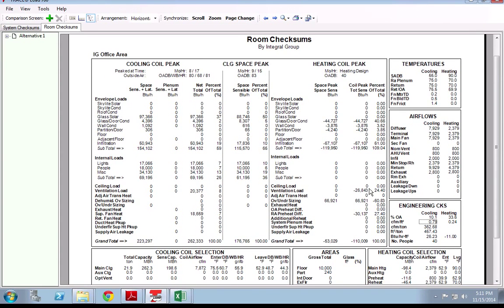The heating loads, we can start to look at these and see the space heating capacities and then the ventilation included heating amounts. Heating just occurs when there is no outside direct radiation and it's at the design condition. So there's no date associated with the peak heating value. It just is always 40 degrees. It also assumes that it's the worst scenario. So there's no internal loads and all our fresh air is coming in.